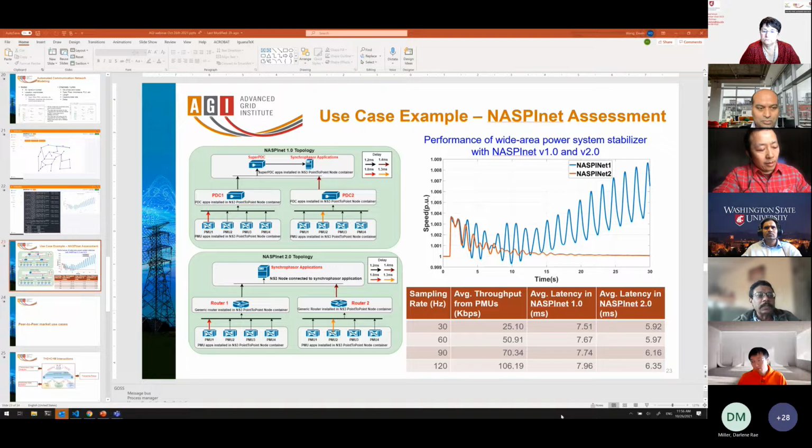And so you can translate the milliseconds, or whatever the time lag is, into the compensation angle in terms of the phase, and that will give you a good indication whether the lag is going to matter in terms of changing the response. I just wanted to point out that this is all standard linear system theory, and I'm sure you are very familiar with it. I was just puzzled by the table, but you have explained it nicely.